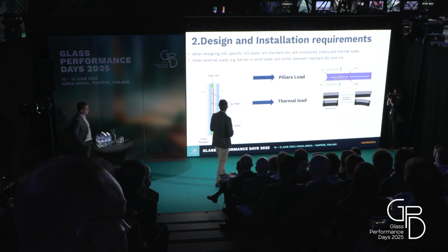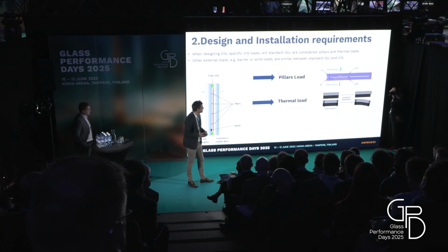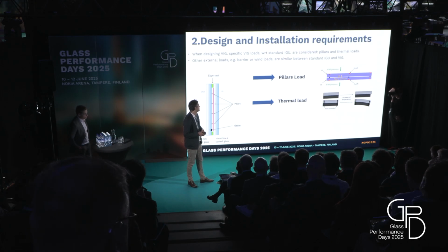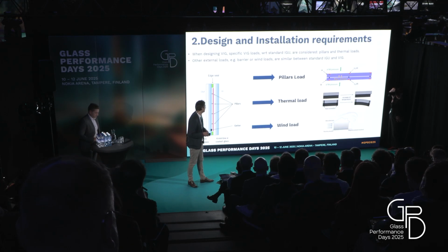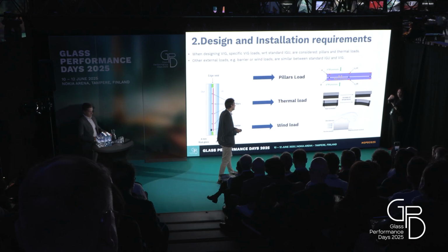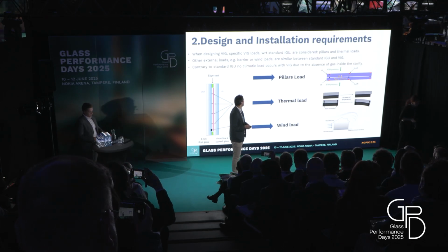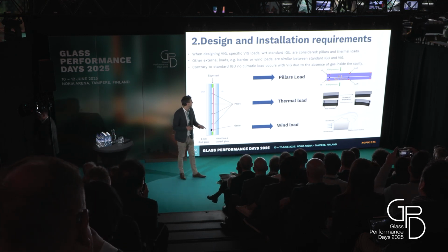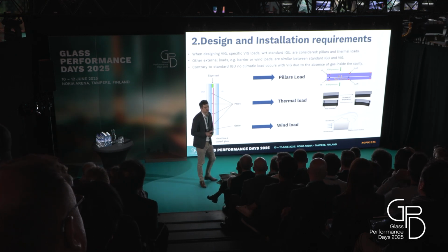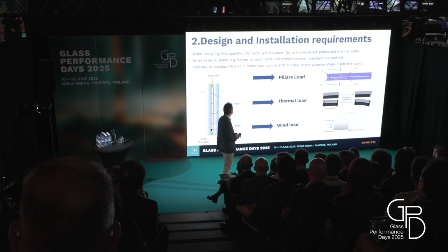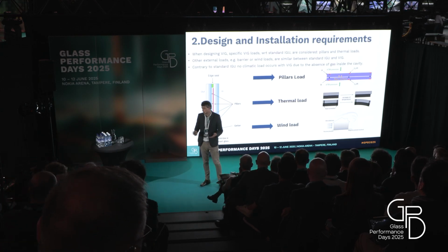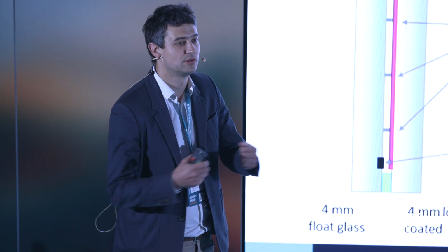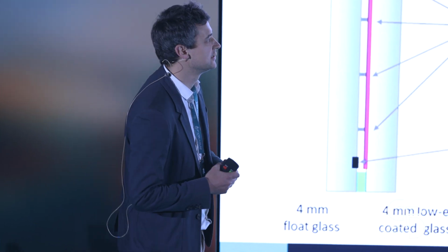Of course, you have to take into account external loads, basic ones that you also consider when you simulate the loads in a standard IGU. I take the example here of the basic wind load. And of course, important highlights. On the opposite of the standard insulated glazing unit, you don't need to consider the climatic load because you have vacuum and so no air in the cavity, so you won't have the pumping effect inside the VIG.